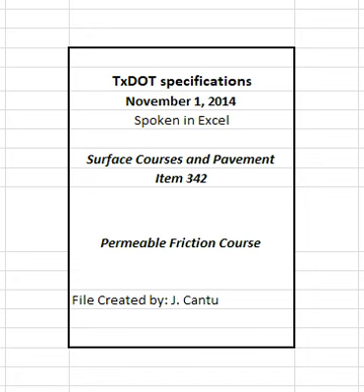4.4.2.1.18 JMF adjustments. If JMF adjustments are necessary to achieve the specified requirements, make the adjustments before beginning a new lot. The adjusted JMF must be provided to the engineer in writing before the start of a new lot. Be numbered in sequence to the previous JMF. Meet the mixture requirements in Table 2. Meet the master gradation and binder content limits shown in Table 4, and be within the operational tolerances of JMF2 listed in Table 5.